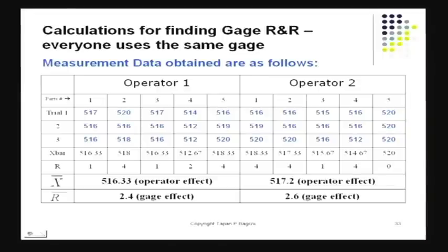Part to part variation has been neutralized by summing across, and of course gauge to gauge variation has also been averaged out by doing this. Now this is the overall average that is produced by the operator. It turns out operator 2 produces a different reading there. Now the difference between these two readings is really attributable only to the difference between the two operators. Therefore this would give me an idea of the variation that is attributable to reproducibility, and we'll take a look at that.